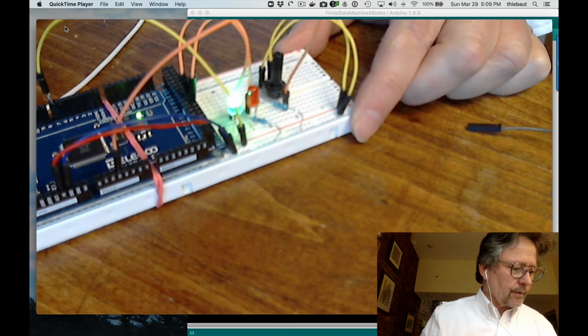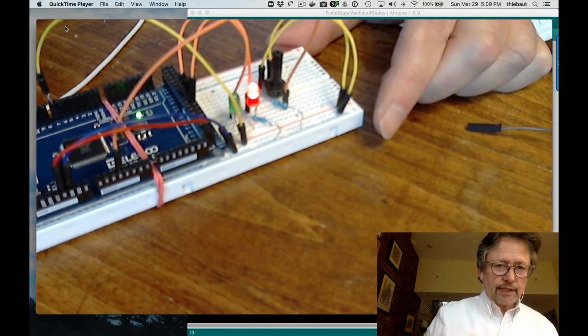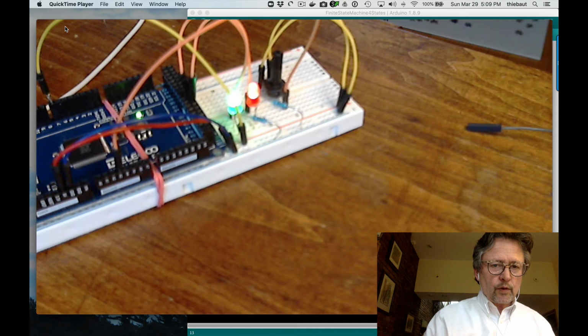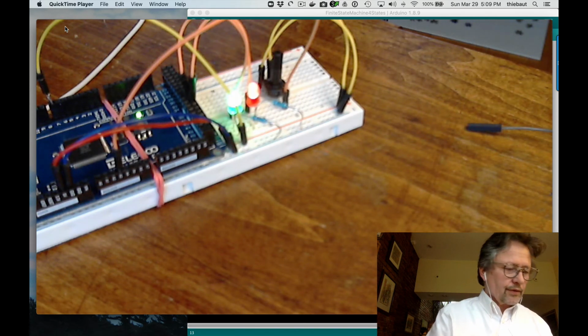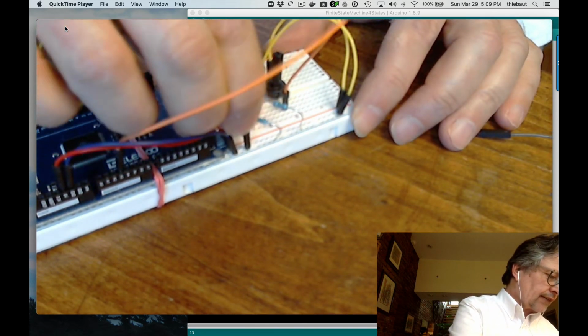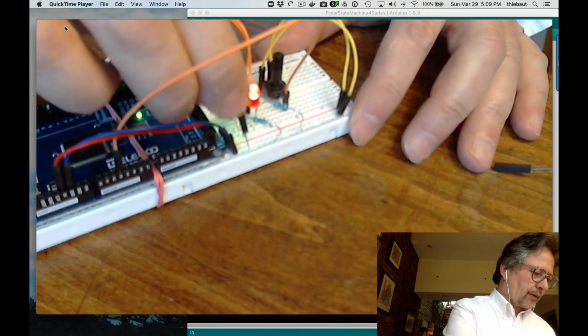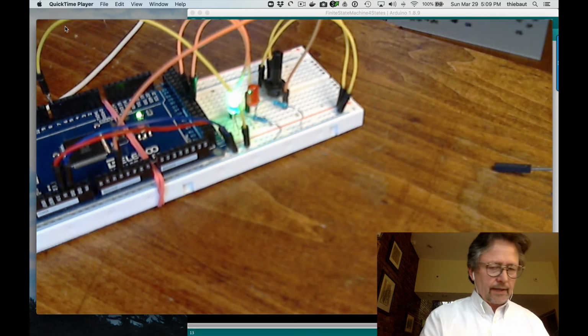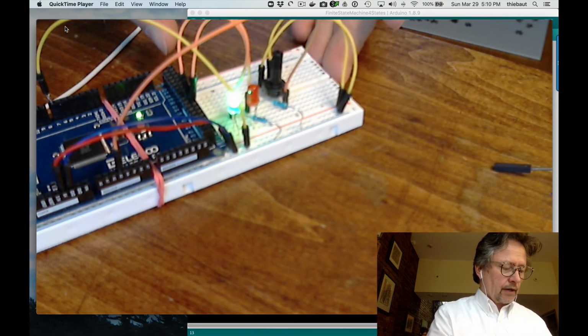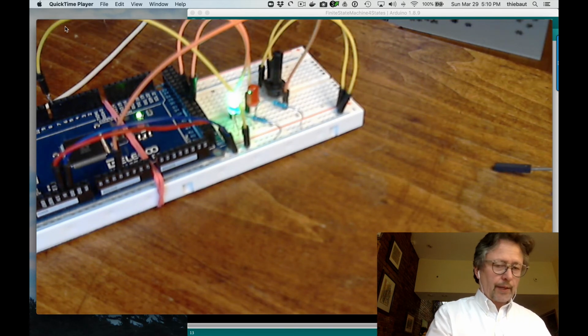When I connect it to +5, you see that my LEDs go binary 0, 1, 2, 3, 0, 1, 2, 3, and I can force that machine to stay in a state if I want. I'm going to wait till it switches, and then close my switch. So here I have the implementation of this finite state machine, but in software.